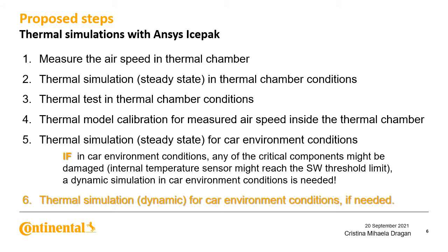If in car environment conditions any of the critical components might be thermally damaged, which means the internal temperature sensor might reach the software threshold limits, a dynamic simulation is needed. If needed, perform a dynamic thermal simulation in car environment conditions.